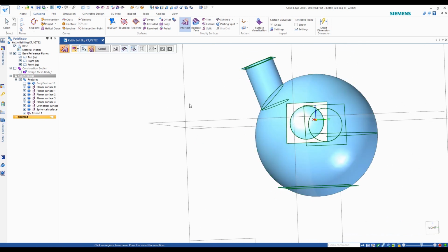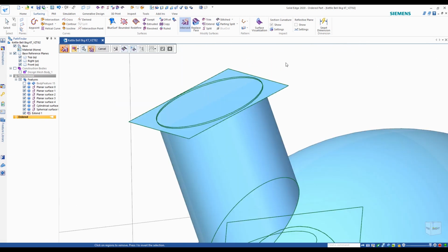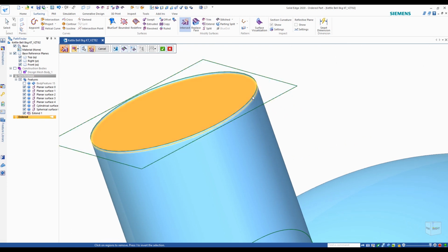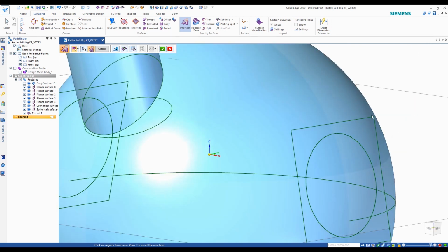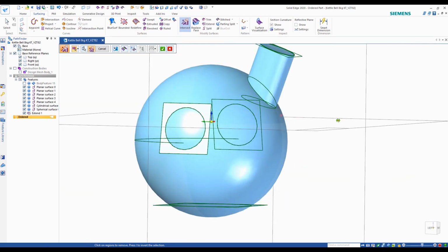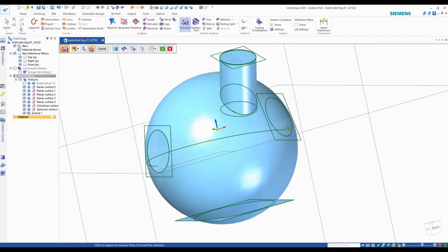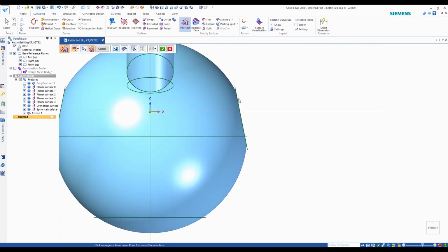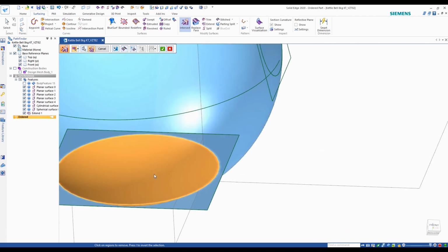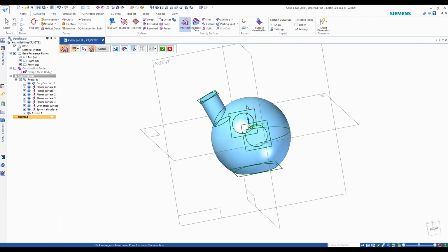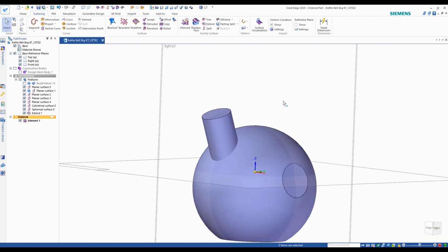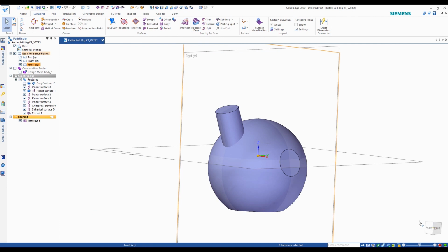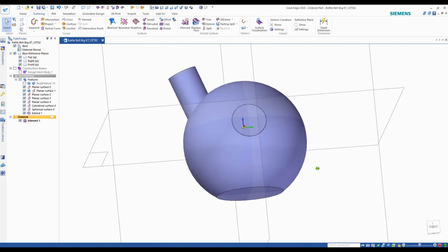And now you just click all the areas you don't want. So I don't want this excess plane here, the little lip on the cylinder. I'll take this one off too. Take this bubble out, this other part and the other cap, and those bottom surfaces as well I want gone. This one and this one. Okay, that looks good. So you can see how this intersect command basically did 8 trims in a single command there. It's a really powerful tool.